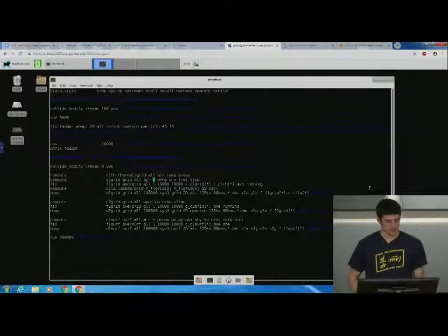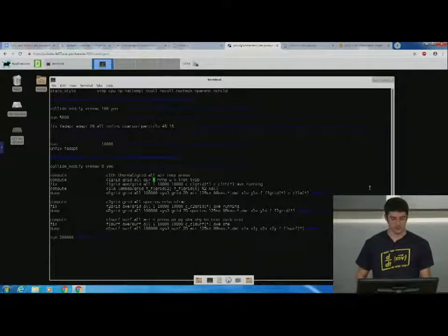And then I'm saying here the variables: number of particles per cell. This is good just to make sure you don't have 5 particles per cell somewhere, that you have 10 or more particles per cell consistently. Number density, x component velocity, y component velocity, rotational temperature, vibrational temperature. Weird thing with SPARTA is that they implemented translational temperature and pressure a bit late. So instead of putting it in here, they introduced this new command that basically all it does is compute translational temperature and pressure. So you want to include this command here.